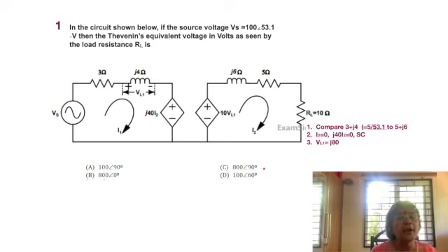Thevenin's voltage? As mentioned earlier, there's no drop across 5 plus j6, so there is only the voltage 10 VL1, and we already saw that VL1 is equal to 80j or 80 angle 90, so 80 into 10, 800 angle 90. Okay, so option C is the solution, and it's actually very easy because of the ease of doing problems that have been introduced in this problem.